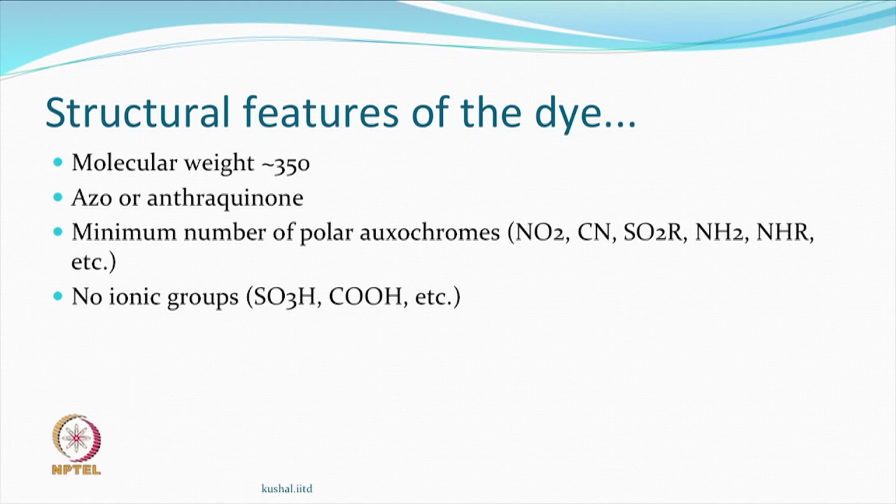So, that when you increase the temperature, kinetic energy will increase, any small bondings that they have will break, molecule will be free to move to the vapor and then go to the fiber surface and then go into the fabric. Ionic groups are obviously stronger than hydrogen bonds or van der Waals forces. If you have only van der Waals forces, it will be nice, they will evaporate faster. If you have a smaller molecular weight, it will sublime faster. So, this is how you people will be looking at some of the dyes in their features.